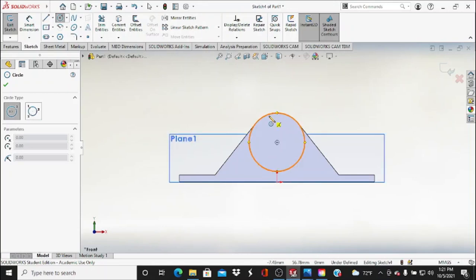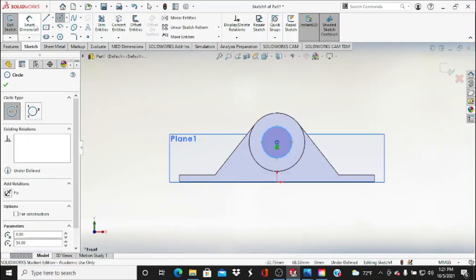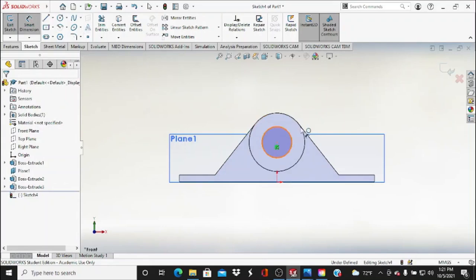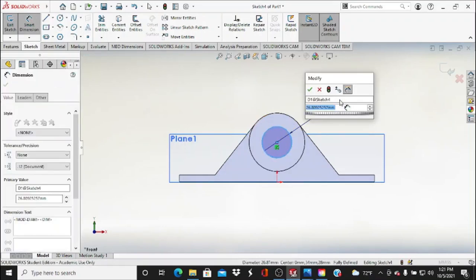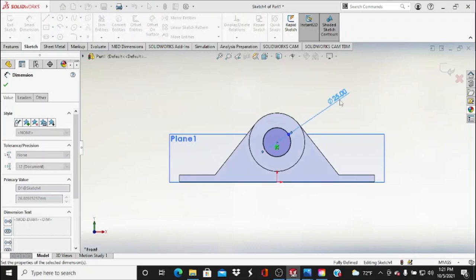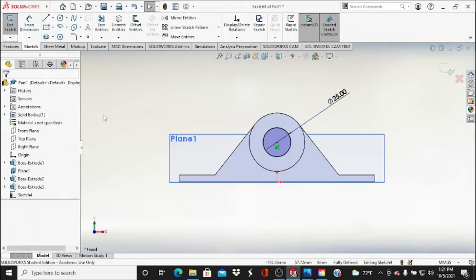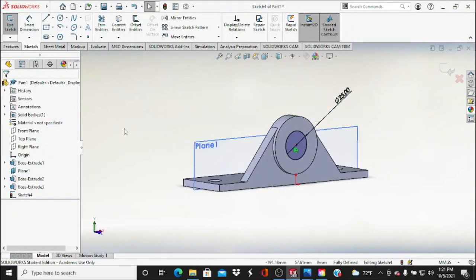It'll highlight the entire orange of the exterior line. We go to the center, click it, and then we bring out our radius, and our radius before was 25. So bring that one up here. Type in 25, enter. There we go. Check it. And we are good.